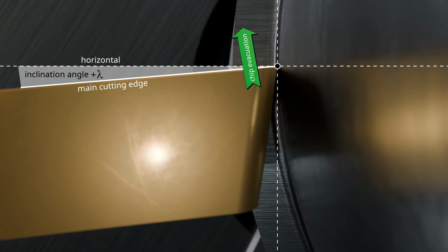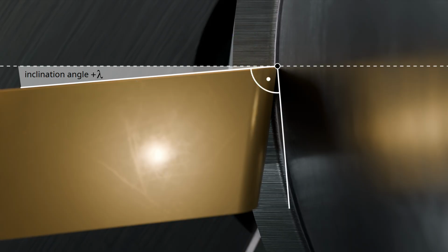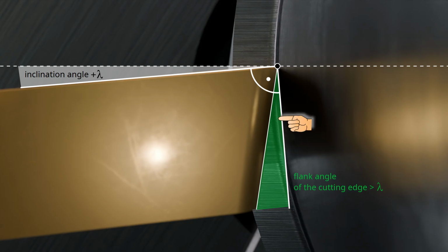In principle, not every indexable insert can be positioned to allow turning with both positive and negative inclination angles. For positive inclination angles, the flank angle of the cutting edge must necessarily be larger than the inclination angle itself. Otherwise, the flank face would rub against the workpiece surface. Inserts used under these conditions are referred to as positive inserts because they are designed for positive inclination angles. These positive inserts essentially have a sharp profile.